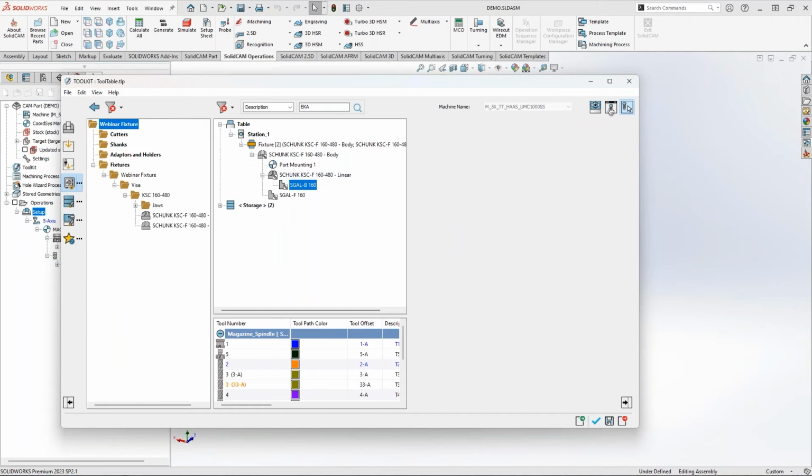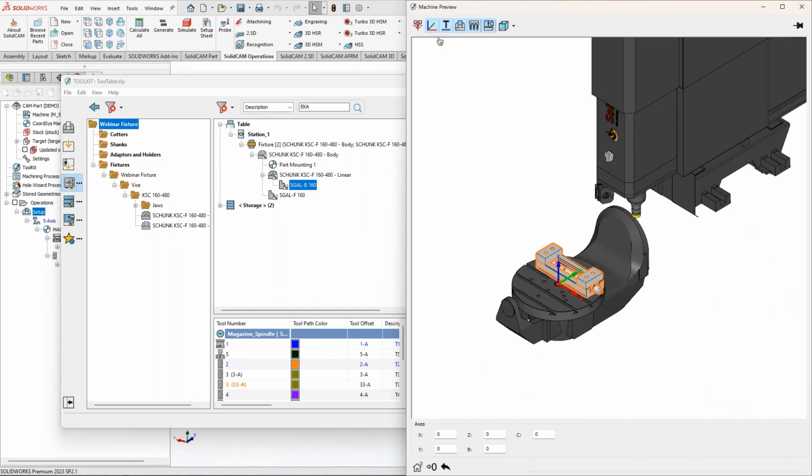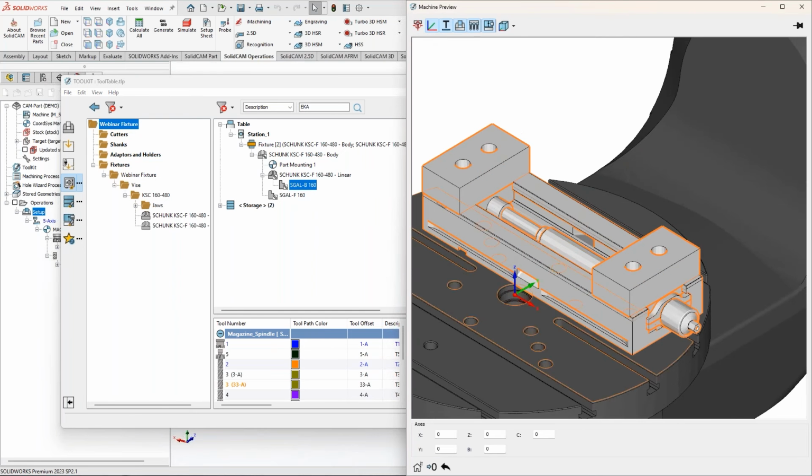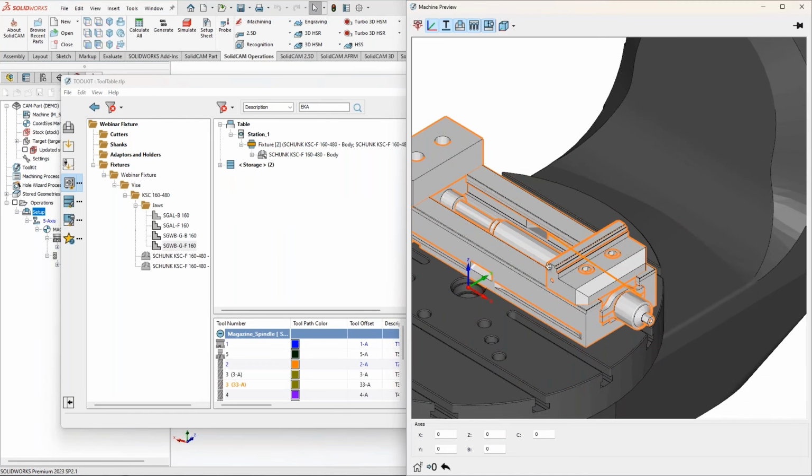So we have different jaws, right? So I'm going to open, click on this, and replace those jaws. I have used this that I can consider like a soft one, and this is the fixed one. So I'm going to take it, and by the way, a good recommendation: take it on the icon, not on the text. There are some different functions for that. So I hold the Alt click and just replace it, and the jaws just replace. Then I'll do the same for the movable one. Just hold it, Alt click. Did I replace it the same? Oh, this is the fixed, and this is the moving one.